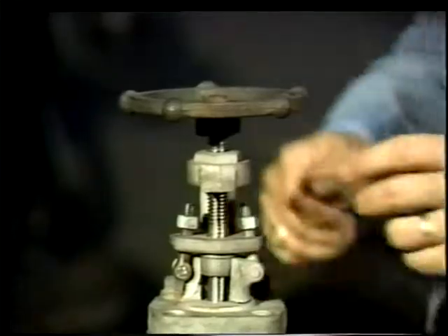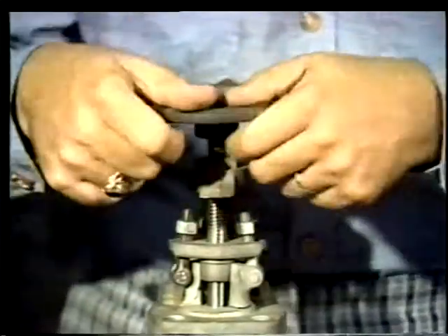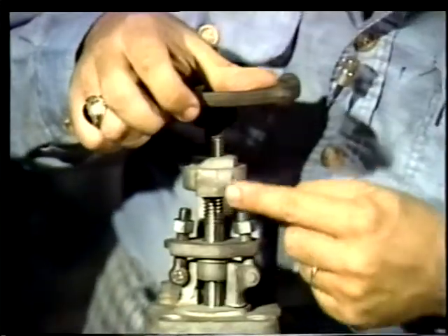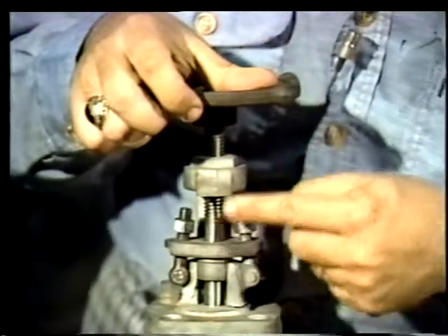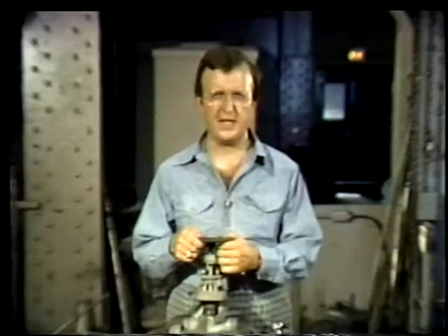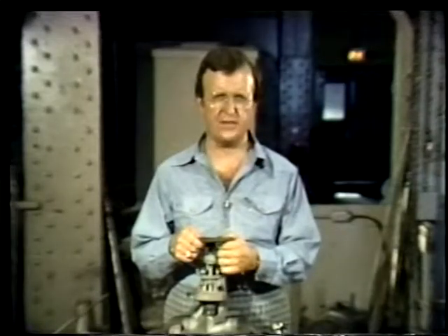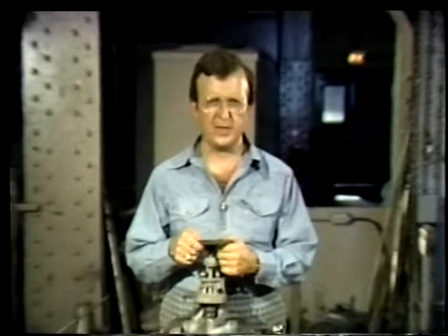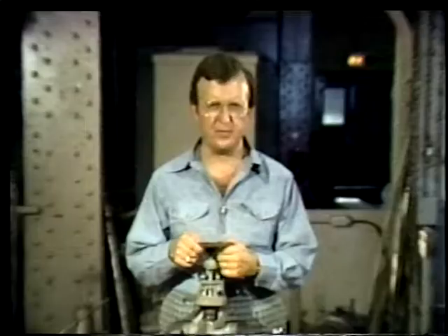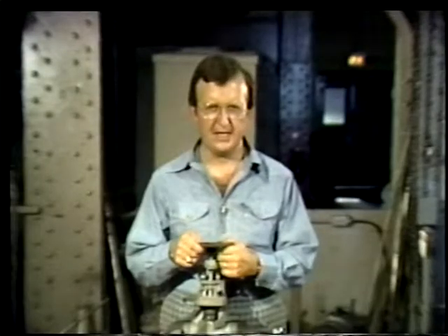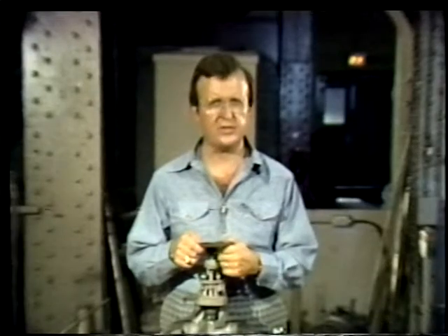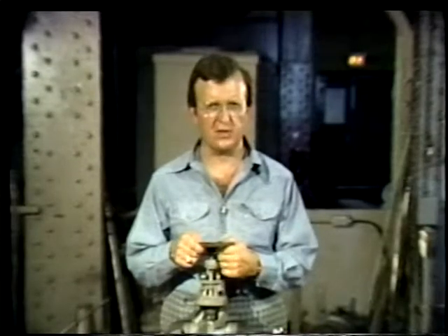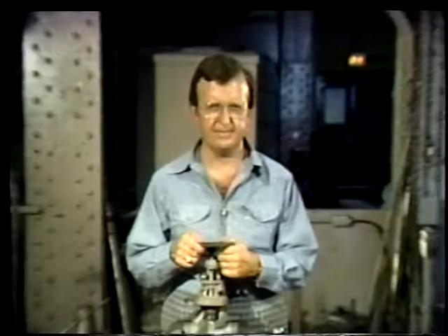Globe valves are usually made with a rising stem, similar to the rising stem of the gate valve. The stem is threaded into the bonnet or yoke bushing. Like gate valves, the specific function of a globe valve determines the material used to build it. You'll find more information on the types of globe valves and how they're made in your text. The preceding types of valves are good for high pressure and high temperature. The following valves are used for low pressure, low temperature application.